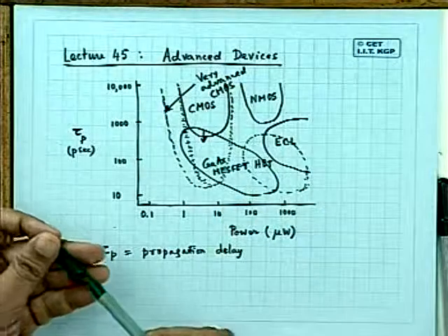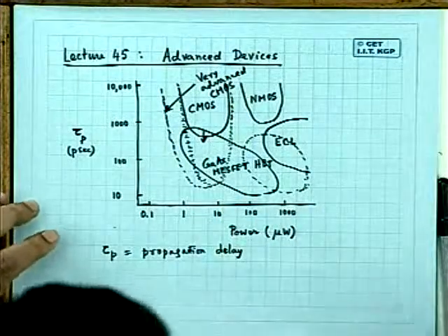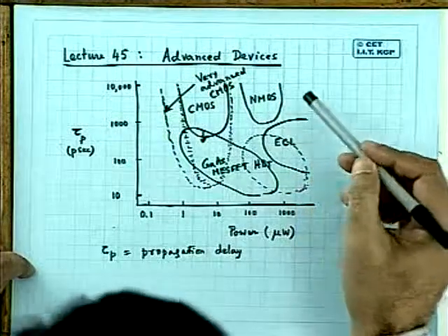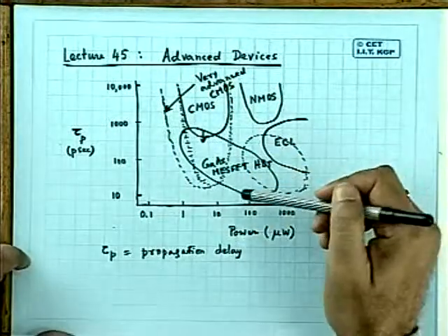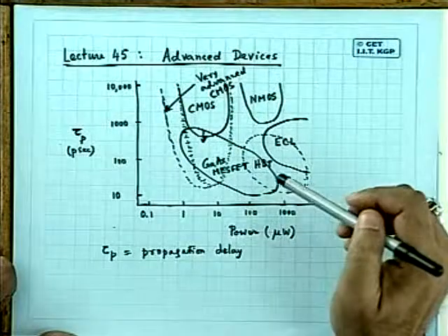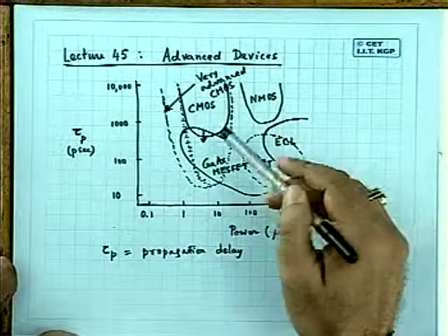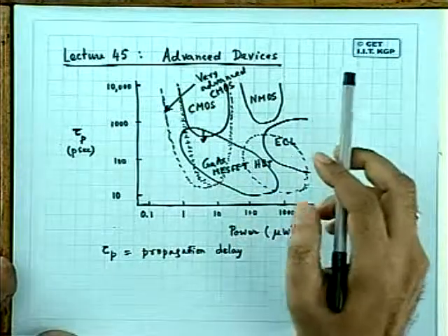You see that here the superiority is, if the CMOS technology had not scaled down to ultra small sizes, then gallium arsenide with even 1 micron technology could achieve very high speed. At the same time, with proper design, it could have very low power dissipation.